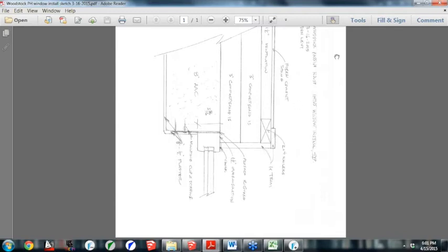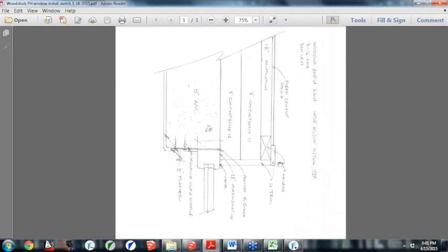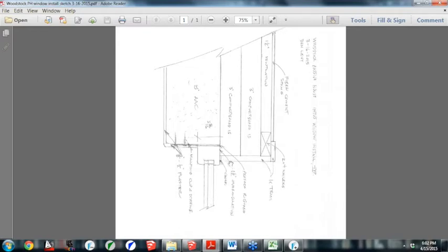So the window reveal here is at least, let's see, 6, 7.5. It's probably 8 inches, maybe a little more. So we're going to input 8 inches for the window reveal, and that is the depth from here out to here. There's the depth of the reveal, which we have is about 8 inches, and then there's a distance from the glazing edge to the shading edge. So that's from here out to here. So this short little distance right here. It says the window's over insulated 1.5 inches. So if we have like a 3-inch frame, let's say the depth, or I'm sorry, the distance is 1.5 inches.